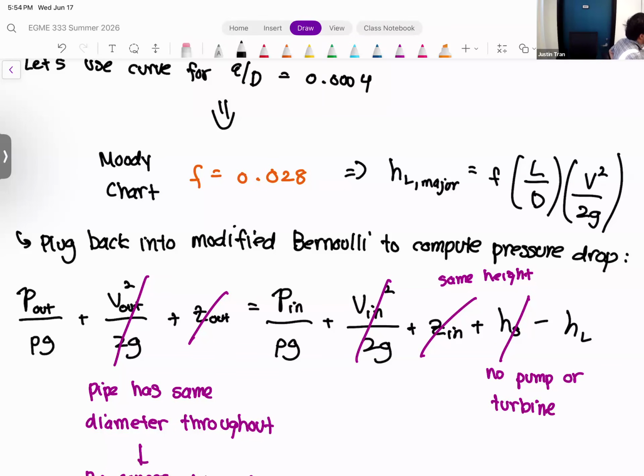I was trying to figure out a way to use the vacuum to pull the exhaust out faster. Oh, I see. Therefore creating more inflow of fresh air into the actual engine. Got it. In that case, having a larger outlet is going to help, just because there's less constriction. If you go into a 4-inch, then you have more atmospheric air exposed to it, and you create a larger wake, which is going to suck more air out of that.